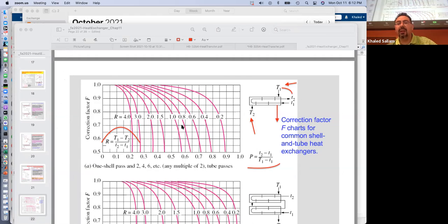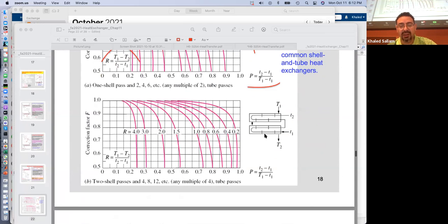So, heat transfer. Q is UA times the logarithmic mean temperature difference, for counterflow and parallel flow. For any other configuration, shell and tube, double shell, and you look here at this double shell, they will tell you it's 2 shell and how many tube passes? 1, 2, 3, 4. Well, it could also be 1, 2, 3, 4, 5, 6, 7, 8, right? I mean, it can be 4 or 8 or 12. You can add more tube passes inside each shell.